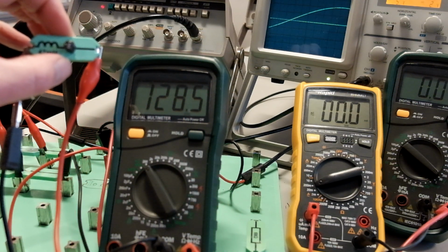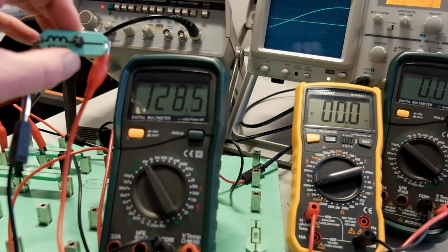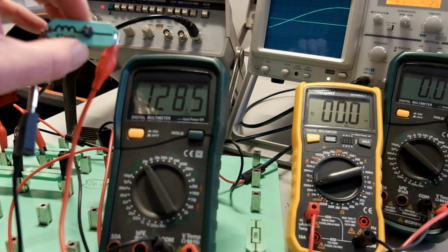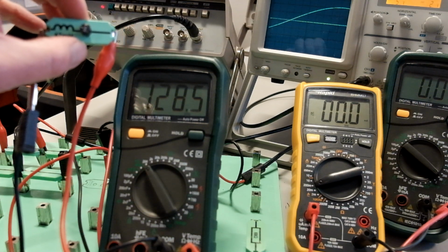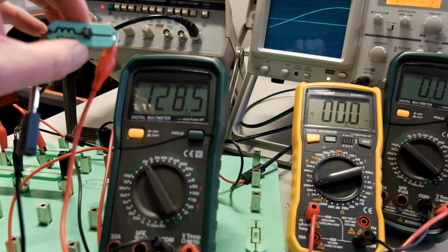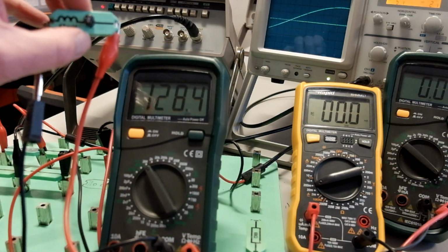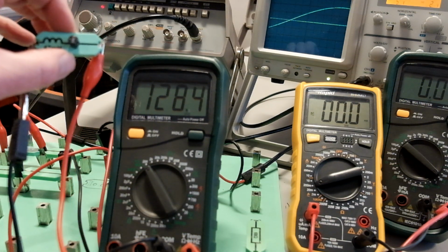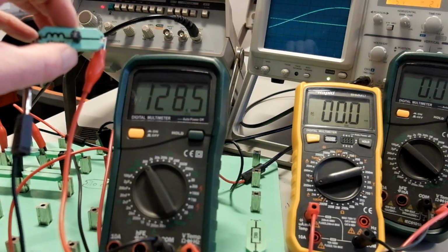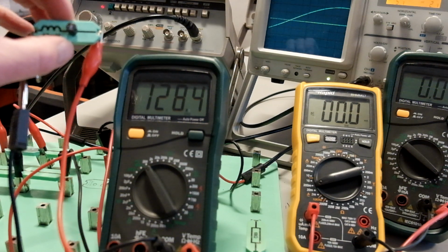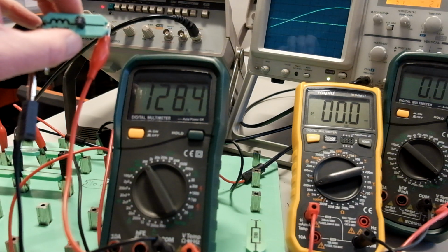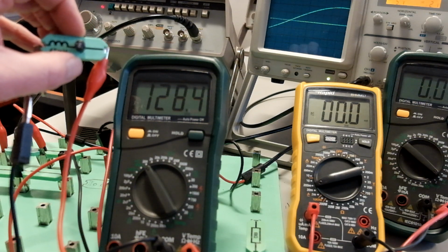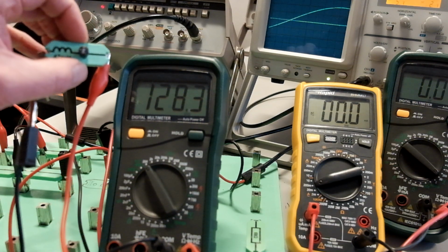What we've got here is 128 ohms of actual opposition to current flow, simply from the length of the wire and the cross-sectional area of the wire. That is significantly different to 0 ohms. So the circuit theory uses 0 ohm resistance for the inductor. In the physical circuit, it's actually 128. So that explains why the current is so significantly different, and the voltage across the resistor is significantly different to circuit theory. So through analysis and a bit of measurement, we can work out exactly what's going on.